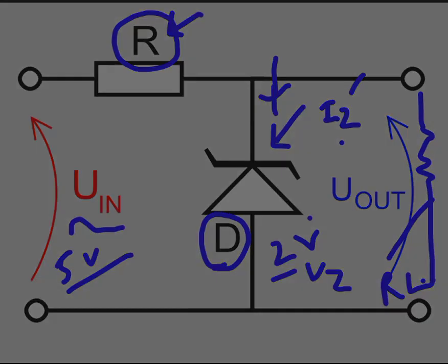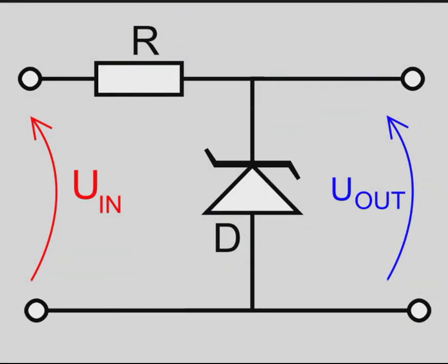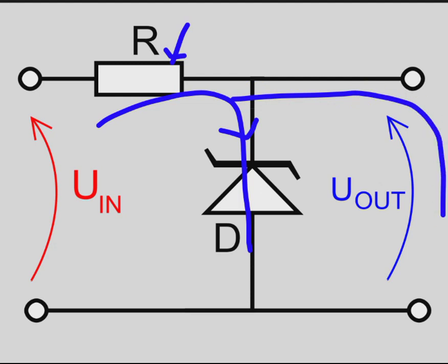The thumb rule is that you have to make sure the value of the resistor should not be very small, because remember we have said that this resistor R is to limit the current flowing through the Zener. If it is too low, then a large current can flow through the diode, and also through the load. So this is not an optimum way. It may damage your diode or the load that the current will flow through.